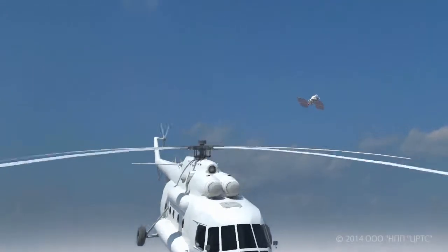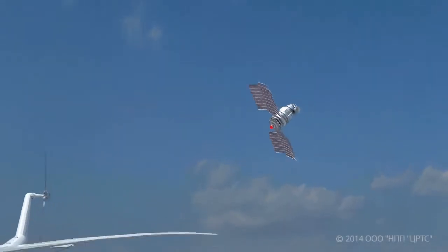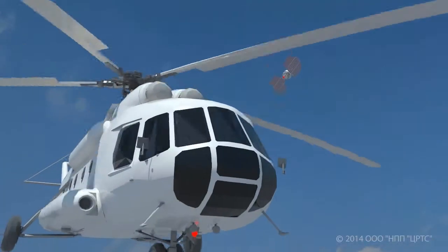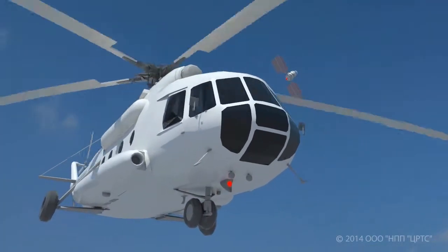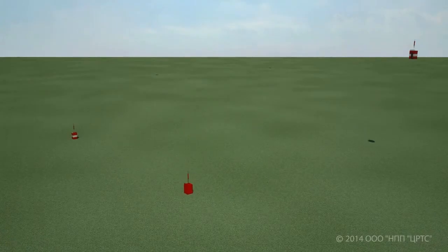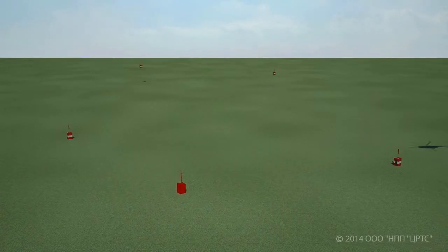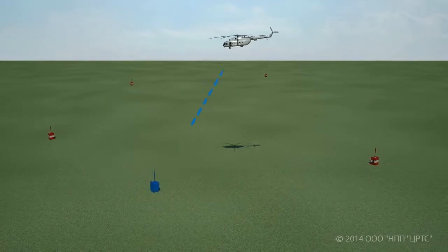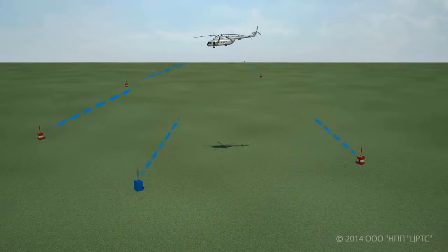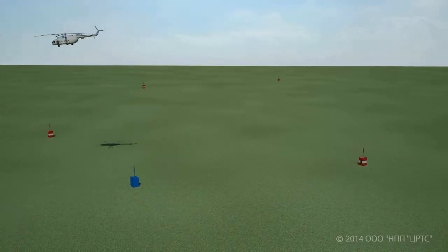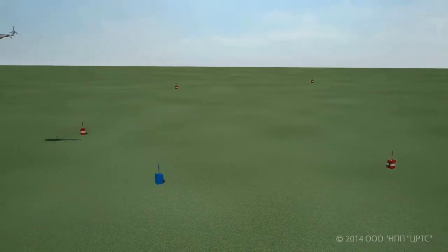At the same time, ADS-B technology has certain drawbacks. First of all, it is dependent on signals of satellite systems, as well as on the operation of the aircraft navigation equipment. Multilateration surveillance systems (MSS) consisting of several land stations are free of such drawbacks. The principle of MSS operation consists in determining the coordinates of the aircraft based on the difference between the reception times of the signals at the different stations.